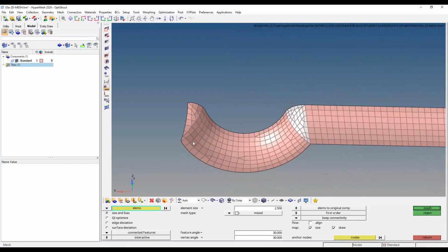And why that can be the case comes back to what we talked about a little bit yesterday and how HyperMesh is determining element stiffness. It determines element stiffness first from the area or the volume of the element given its shape. Then it applies a material property to that, and that's what's determining stiffness. So the reality is the individual element shape is dependent, for better or worse, on the results you're getting. So you really want to make sure that not only are each of those elements looking the same, but even global features like this entire surface of elements looks the same as its neighbor if that surface is going to repeat itself there. Consistency is key.